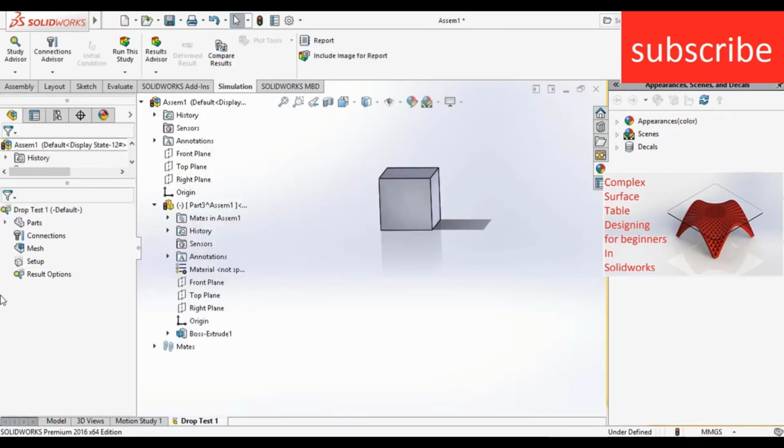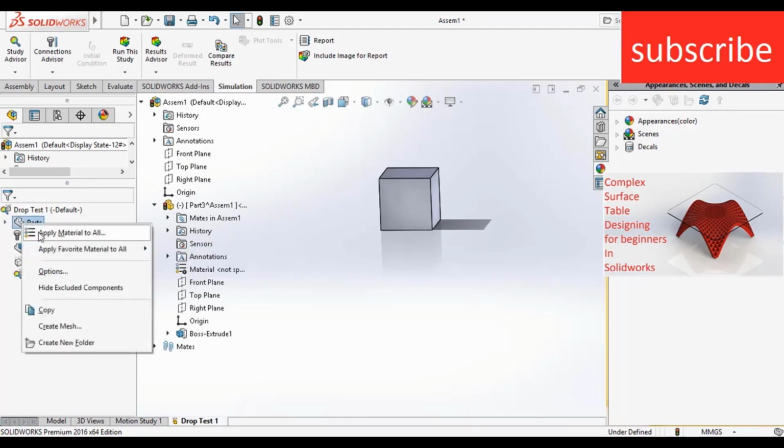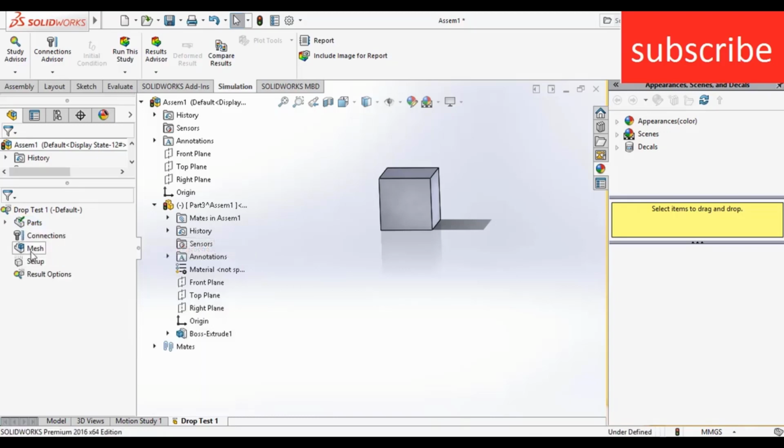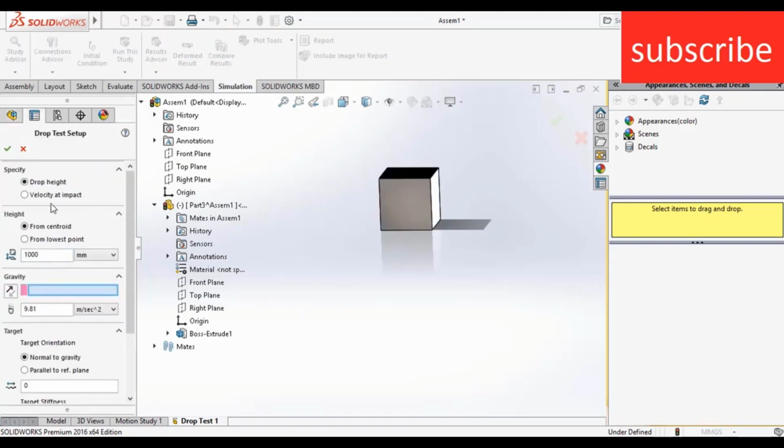After that what we need to do is right click on the part, apply the material as per your requirement. Here I am going to use plain carbon steel, but you can change the material as per your requirement. After that right click on setup, click on define/edit. Here select velocity at impact.